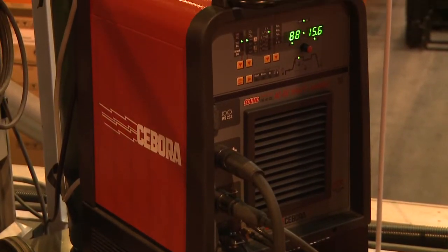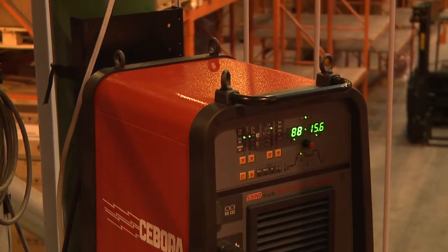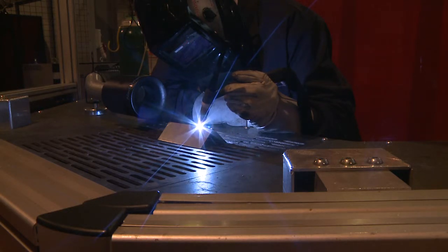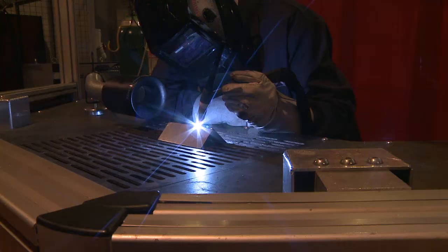The gas flow rate you use in TIG welding should be sufficient to cover the molten welding pool, otherwise you'll have problems with defects in the weld. Typical flow rates for the gas are between 8 and 12 litres per minute. If you're using helium, it could be double that amount.